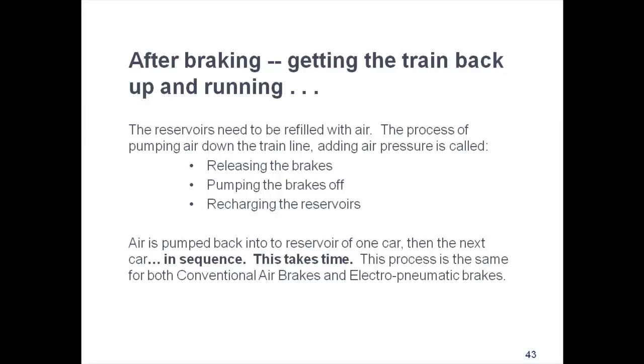This process, which is the same for both conventional air brakes and electro-pneumatic brakes, of pumping air down the train line, is described by these phrases: releasing the brakes, pumping the brakes off, and recharging the reservoirs. There are occasions when the trainmen cannot pump air back into the system fast enough to keep the train moving.